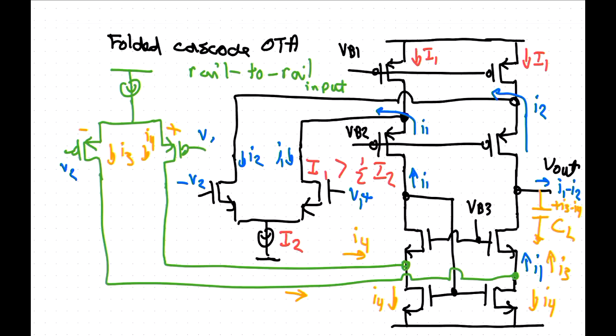I probably should say for the differential pairs here that if you want to do it really well, what you've got to make sure is that the transconductance that you get, which is really the transconductance for the P and the transconductance for the N summed up, that the total transconductance for the amplifier is constant over the complete common mode range. It's easy if you keep the input pair in weak inversion, because then the transconductance is proportional to the current.